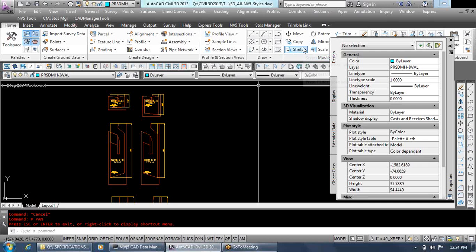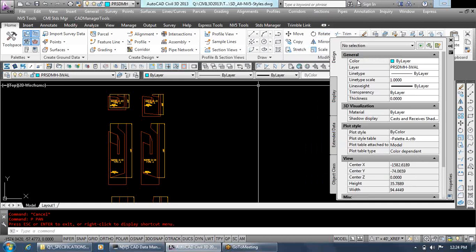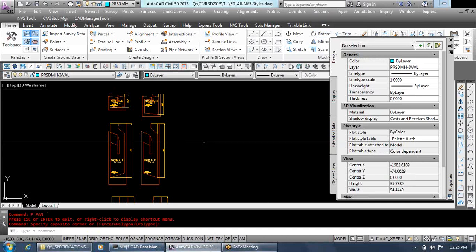When you create your pipe network, be sure to then go back and rename all your individual pipe parts. If you have 20 parts on your storm drain line E, let's say, name that first pipe E-1, E-2, E-3. And that comes into play when you start talking about crossings. You need to know what pipes cross each other, and the only way to do that is with a solid naming convention. So start implementing good naming techniques in your drafting and design.